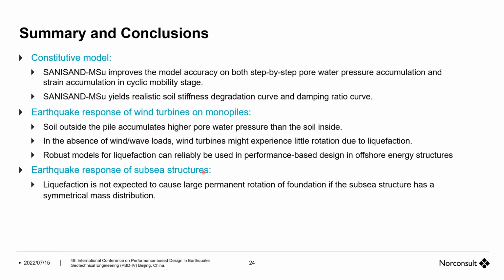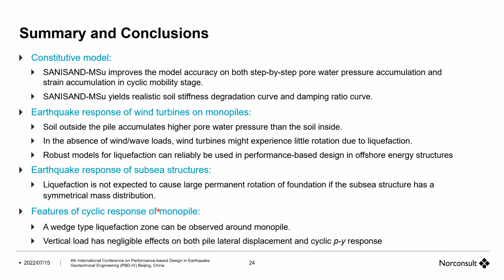Earthquake response of subsea structures in terms of liquefaction is not expected to cause large permanent rotation of foundation if the subsea structure has a symmetrical mass distribution. And features of cyclic response of monopiles: a wedge-type liquefaction zone can be observed around the monopile, and vertical load has negligible effect on both pile lateral displacement and cyclic p-y response.